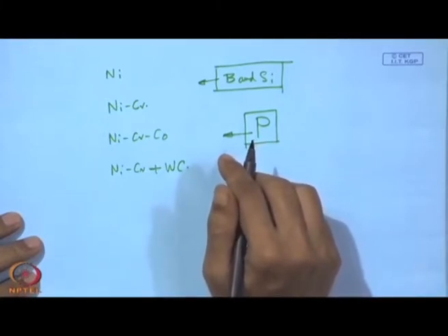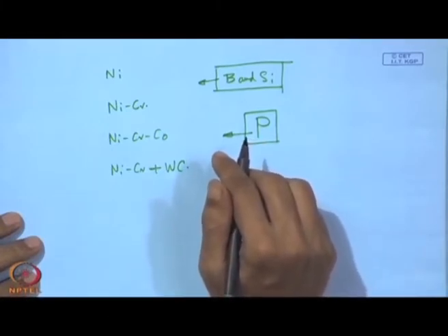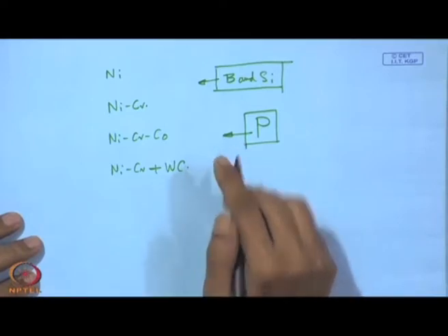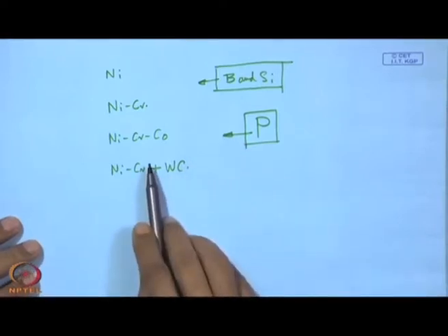That is very important to know, because the melting point of nickel or nickel chromium cobalt is quite high, and to attain that temperature is not very easy, or may not be of practical interest. We want the whole processing to be done at around 1000 degrees or even a little below that.